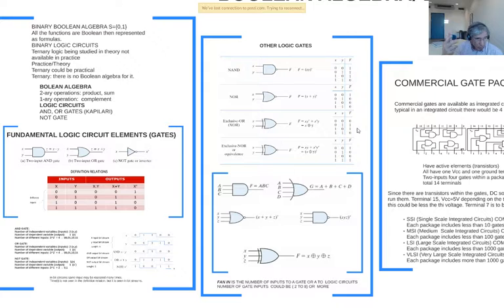That means it could be 0, 0 or 1, 1. If your output is 1, your input could be either 0, 1 or 1, 0. That means different values. From this definition, if you use the first canonical expansion, you get that formula. We can show it by this symbol here, a circle inside a summation operation to represent exclusive OR.